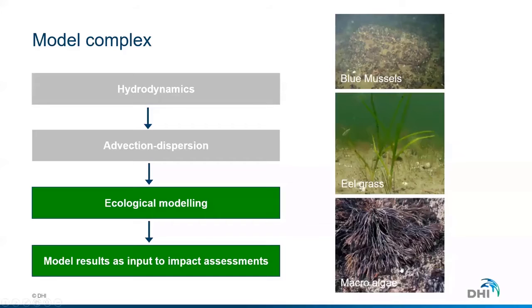The way we have implemented the ecosystem model at DHI is we have models describing the physical parts. That is a model provided by bathymetry, wind, air temperature, point sources, freshwater input, etc. It outputs information on the water level, current, and transport, salinities, and water temperatures. So that's the hydrodynamic model.